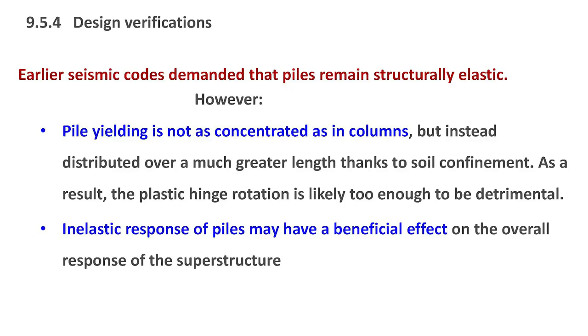And finally, do we allow plastic hinging of the concrete elements, the strictly foundation elements we call? No, we don't allow much structural damage in the footings, but in the piles we have relaxed this. We have actually made this a little bit more unconservative. We do allow some yielding of the piles.